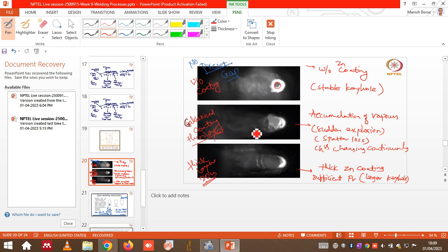That means the weld has variation in the size of the nugget area. Those properties are not good, right? So there are certain strategies the professor discussed: we can maintain a certain preset gap in such cases, so that the vapors will escape through that preset gap.